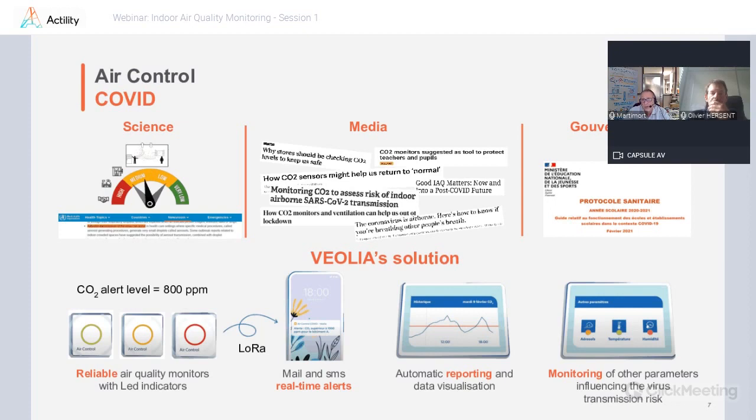And we do the same for VOC for one particular reason: this sensor is not for lab. It is used for ventilation purposes. And if we don't want to ventilate 24 hours a day for nothing, we consider the outdoor VOC level as the best we can get, and that is used as a baseline for the VOC concentration as well, for calibration as well. Okay, thanks a lot.